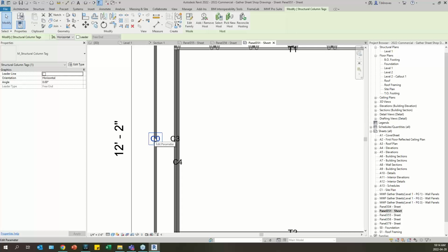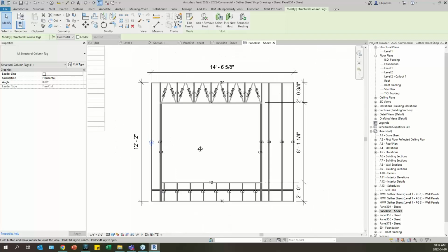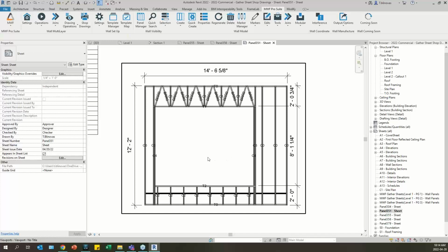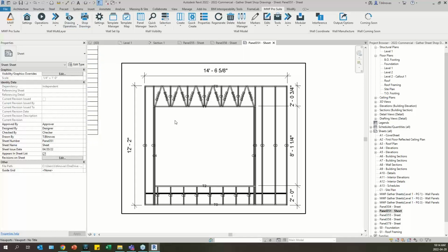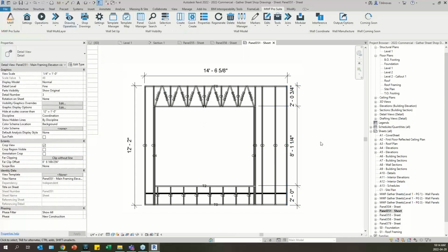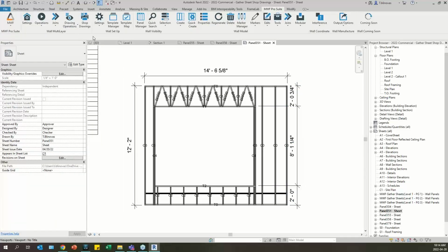You could refer to any other parameters if you want, or maybe two of them, maybe the schedule label plus the family type. So it's going to be up to you. But yeah, that's pretty much what it will do. Usually if you refresh, it will go away. So in that case, you can always go in again, go back to smart tags and just run the command again.